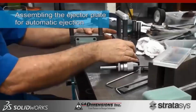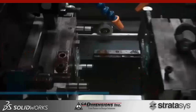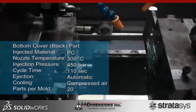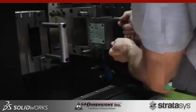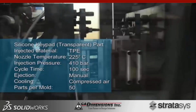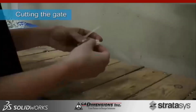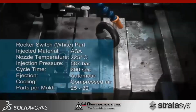You'll be seeing materials such as polycarbonate, ASA, and TPU throughout, but we have customers all throughout our territories and worldwide with Stratasys that are using these materials in a much broader approach and way more materials than just the three that I've mentioned. There's one company called Seufer out in Germany that shoots TPE into their molds and a different type of simulated polypropylene, and they're able to get several hundred shots out of their molds as opposed to 50 here and there.